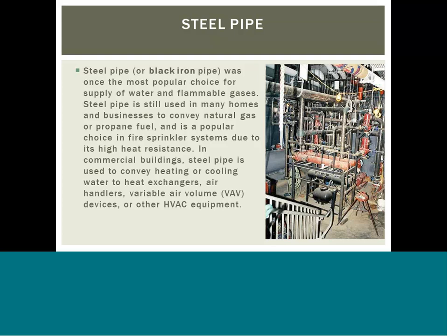Beyond domestic or light commercial settings, steel pipe is often joined by welding or by the use of mechanical couplings made by companies such as Victaulic or Grinnell that hold the pipe joint together via a groove pressed or cut into the ends of the pipes.